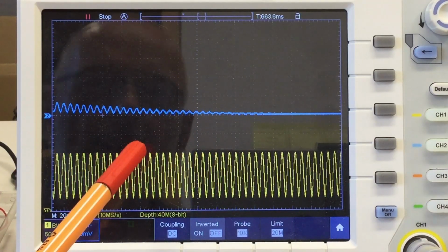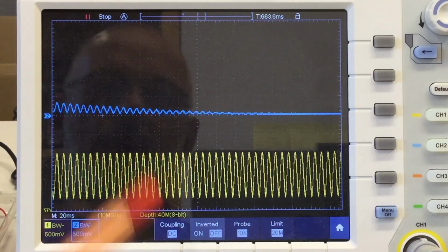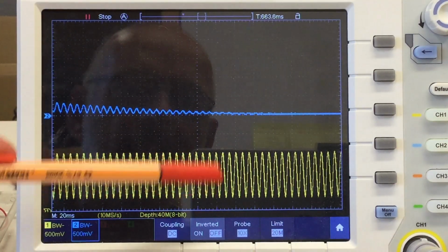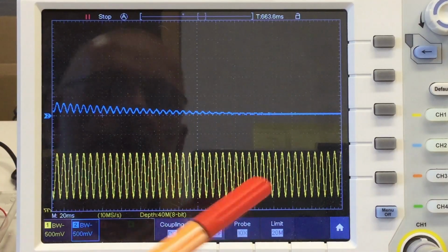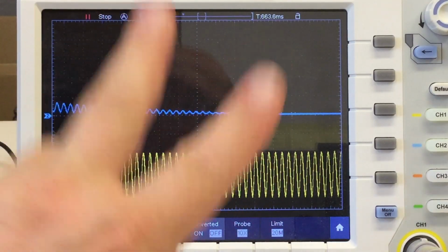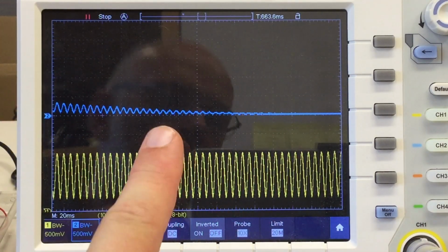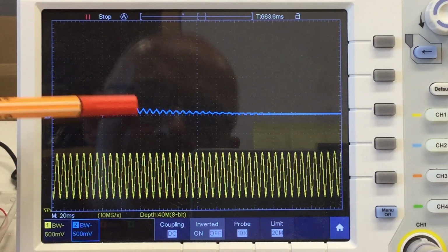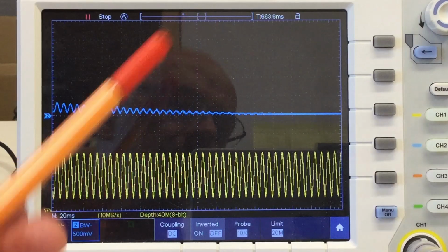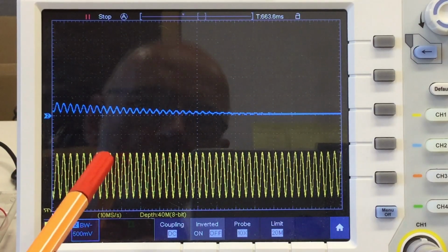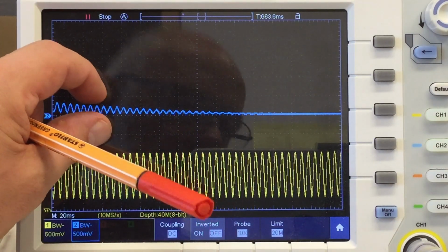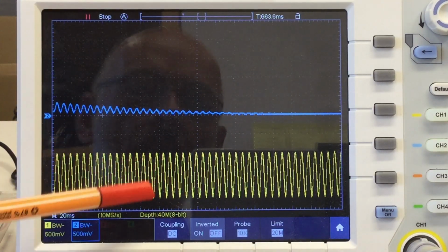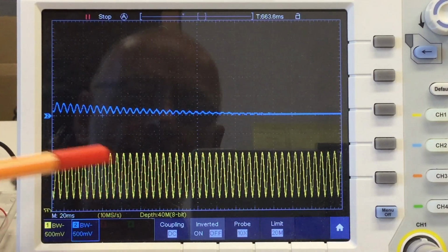Now, when you are asking, Robert, you could do that directly by feeding the appropriate DAC values in here. You are missing 2 points. First, this little sine wave here still has a 12-bit resolution in that little amplitude range, because that's from an analog input signal.